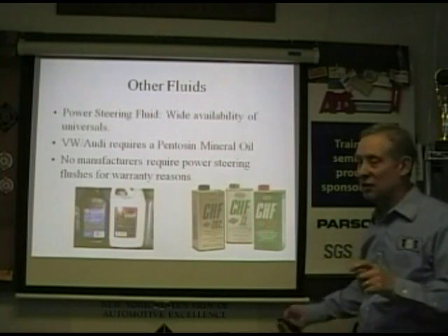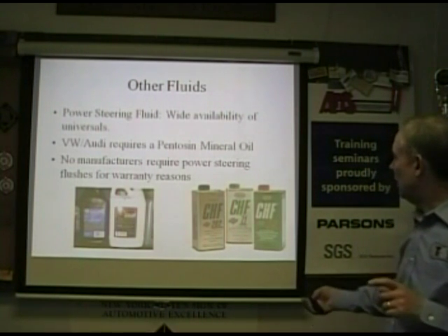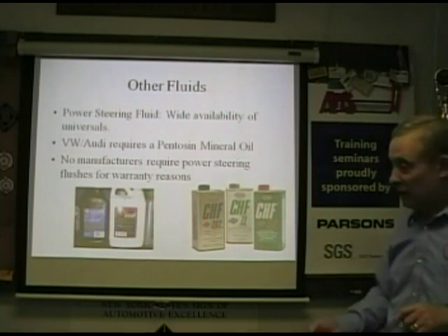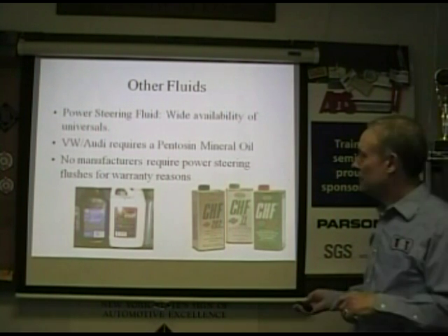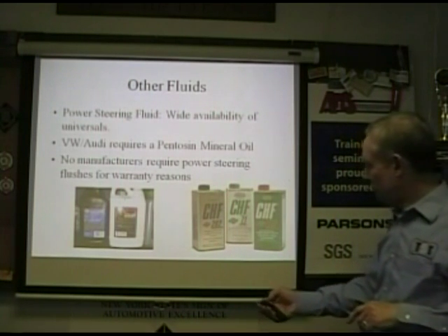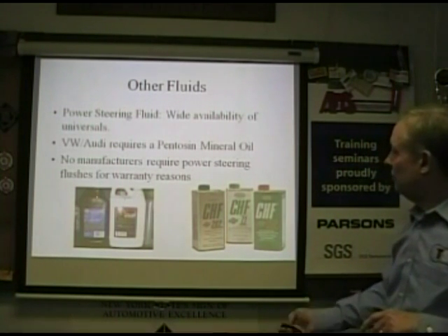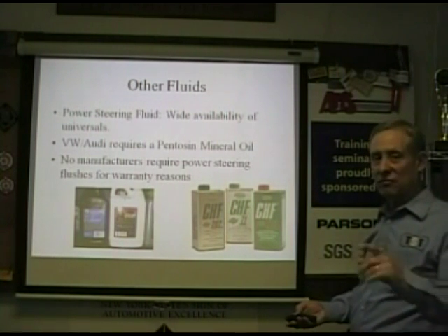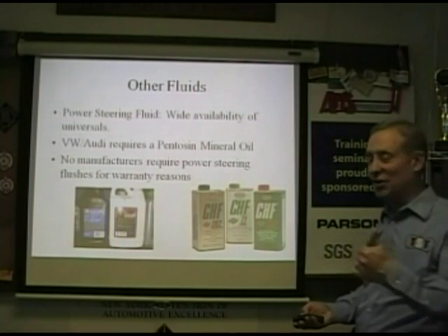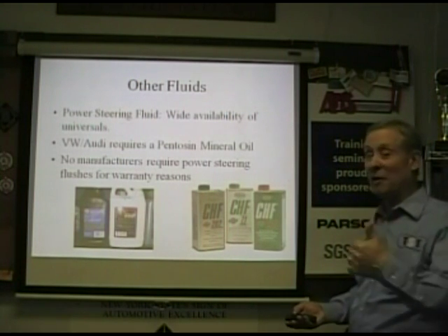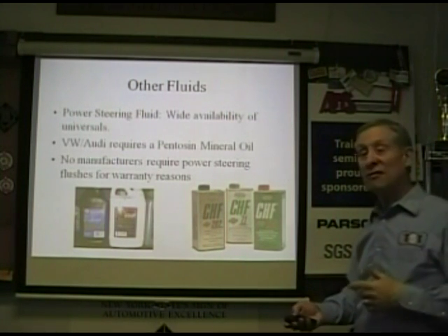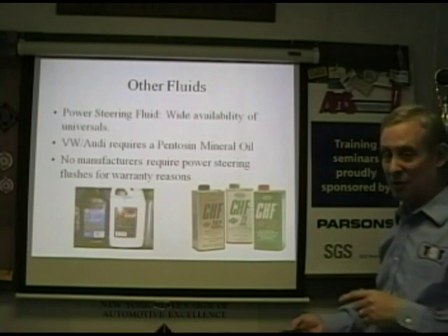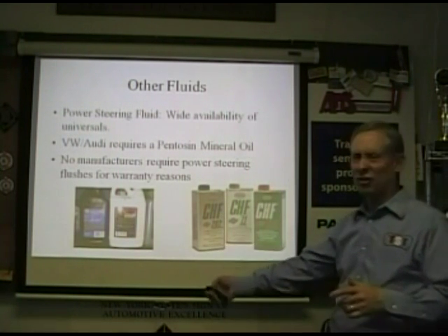7.1 is a non-synthetic, and 11S is a synthetic, but they're both green, and they're not compatible with each other. And the same thing even over there, the Napa and the Run Right stuff. You've got to be careful and make sure it meets Honda spec. Honda's very fussy with power steering fluid, like I said with coolant, just like I said with engine oil. Read the spec, read the label. Don't use stuff if it doesn't have the spec on the label. Don't believe the salesman who says this is good for everything.